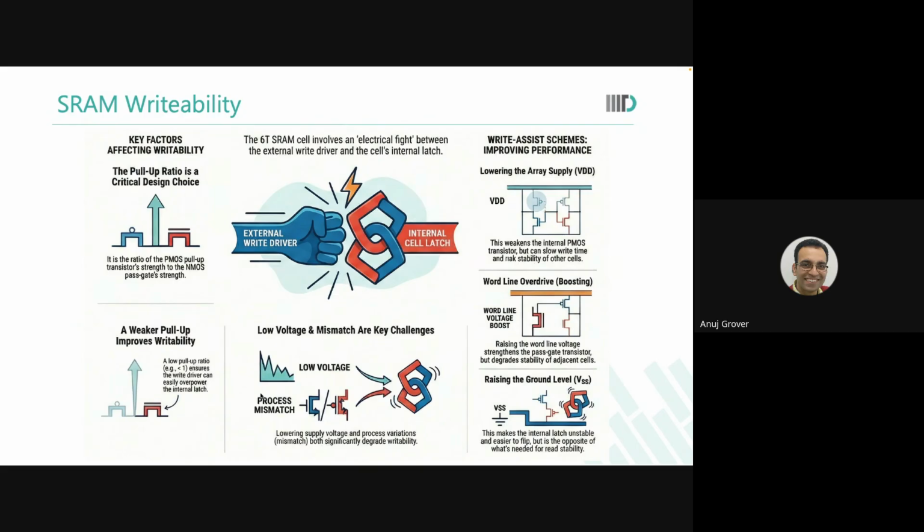Okay, that is something. See, in terms of devices, will you always operate the memory at, let us say, 0.7 volts or 0.8 volts? No. We know about DVFS already. We know that there will be times when I will need very high speed. So in those times, I will operate the memory at 1.2 volts. Am I right? So at 1.2 volts, when I'm operating the memory, what happens? This negative bitline may still get generated.